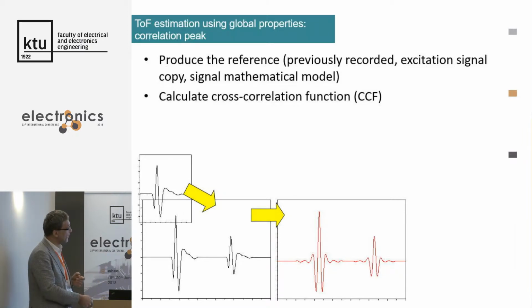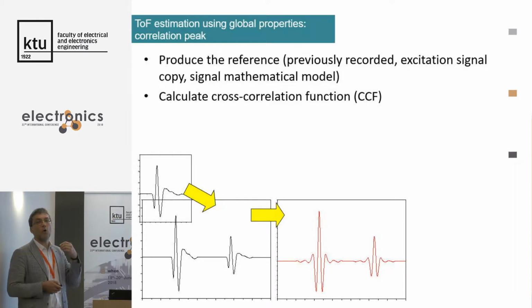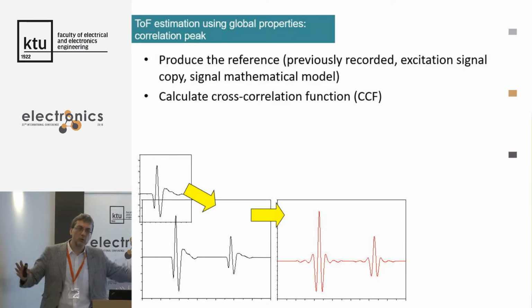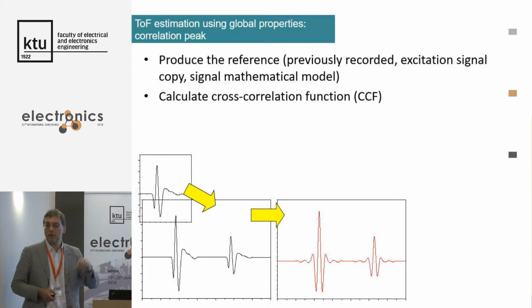So at the peak, which has the best signal to noise ratio, you have all the signal energy. Which means that if the signal was long, you have squeezed all the energy into one point. This means you have very large signal energy, so the noise goes down, because noise is not correlated with your signal.